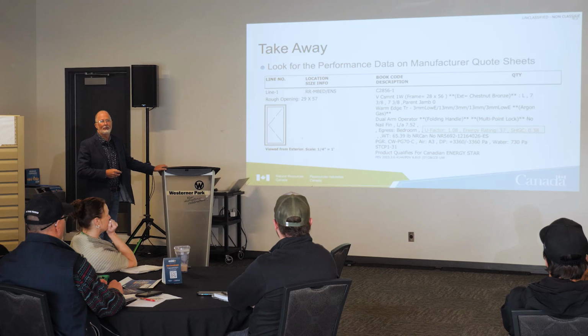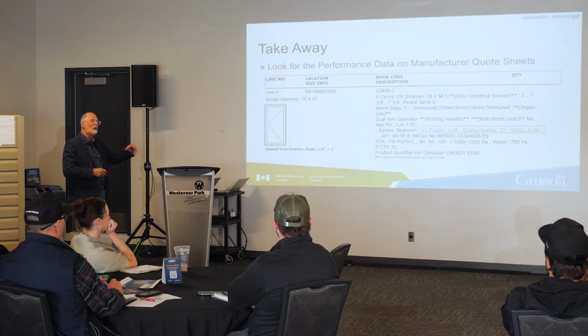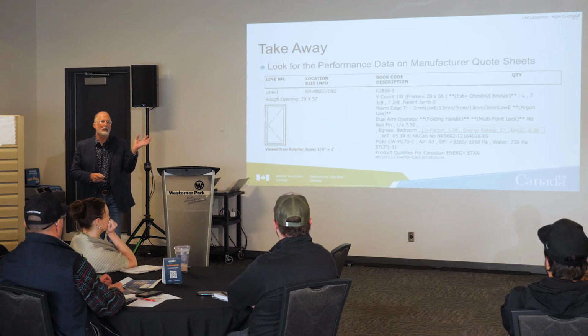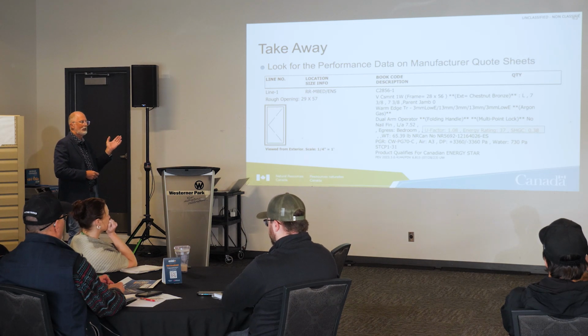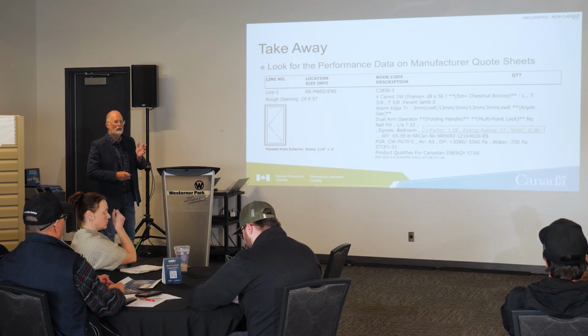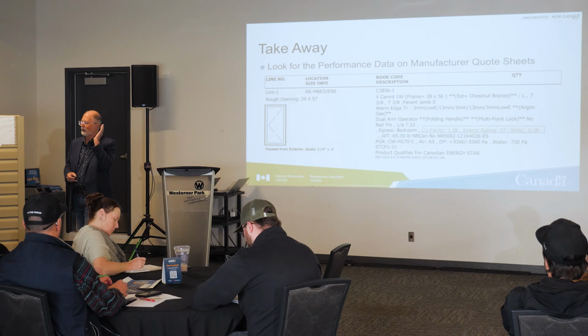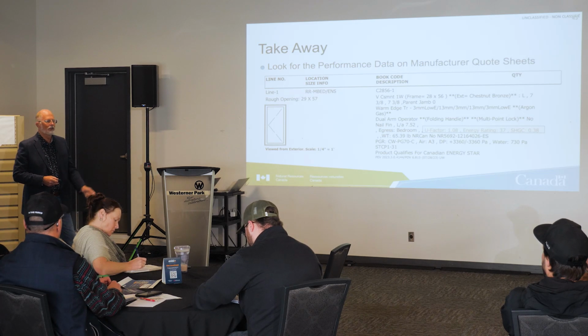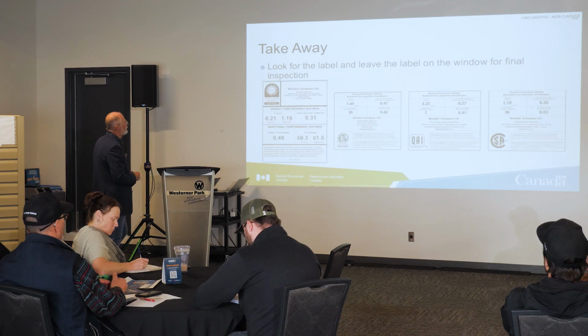Yeah, condensation resistance. Energy rating. You might need an energy rating depending on if you're putting it into a software or not. So those are things now you understand. You might not know where the coatings are on the glass, which would dictate condensation resistance, right? Is the coating on the inside surface? What's the durability of that? If the painter comes along and cleans the windows before the homeowner moves in, and uses a razor blade, is he going to take that coating off? Right, so those are things to think about when it comes to the windows.